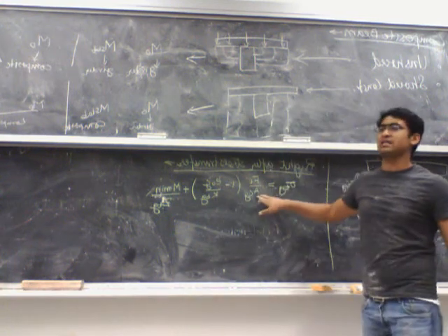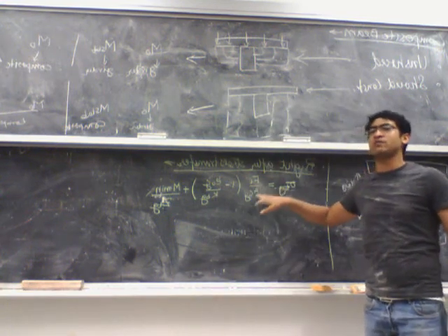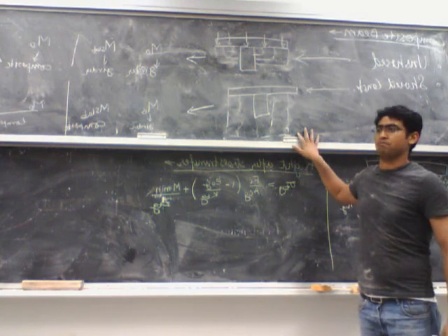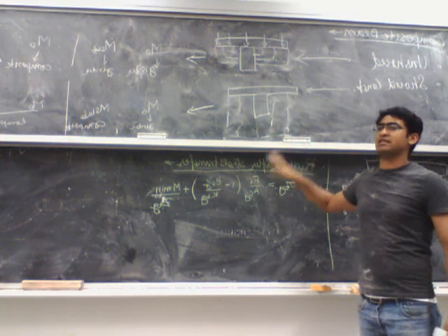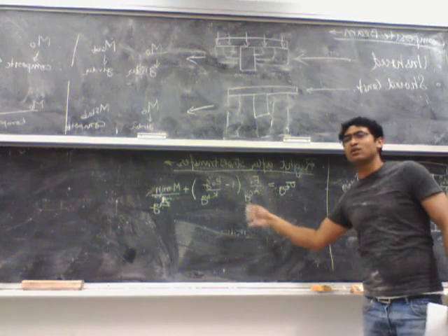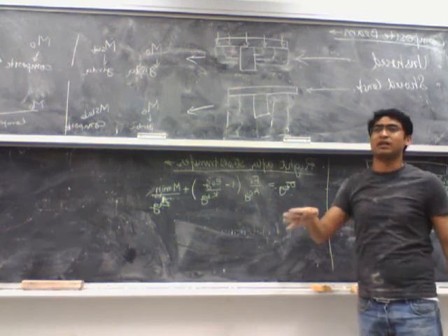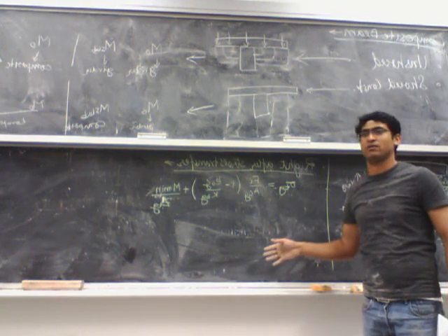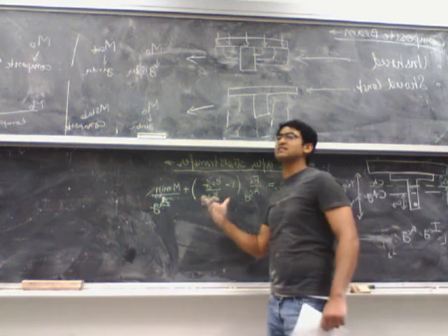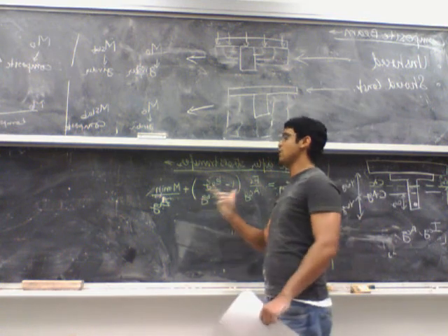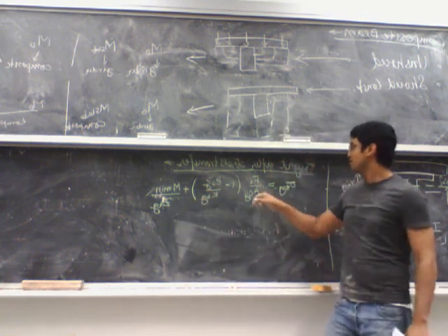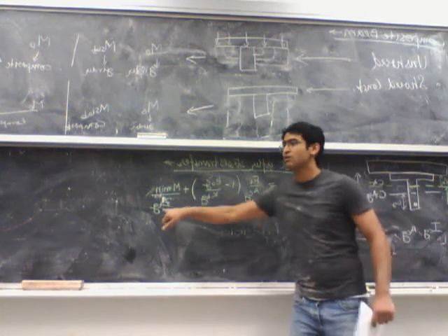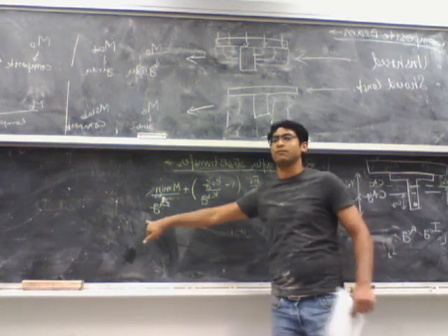So this equation is exactly the same as what we had for a non-composite beam, because at this point the girder doesn't know that it might have a slab later on or it might not have a slab later on. The only difference is we add a G everywhere to make sure that it's the girder only.